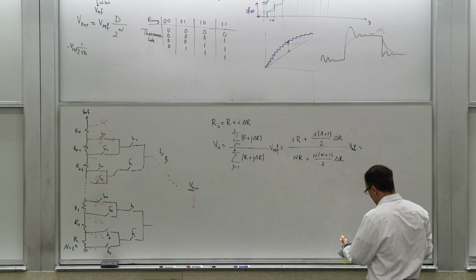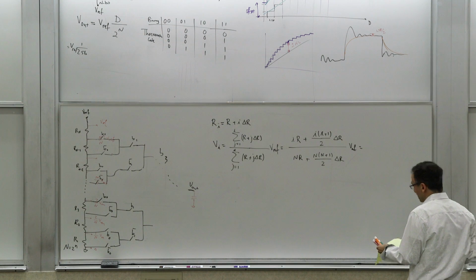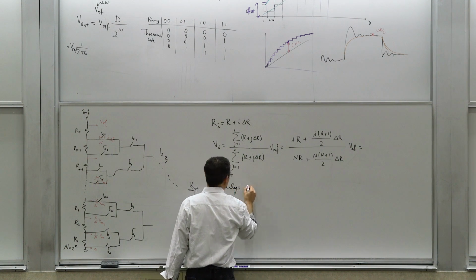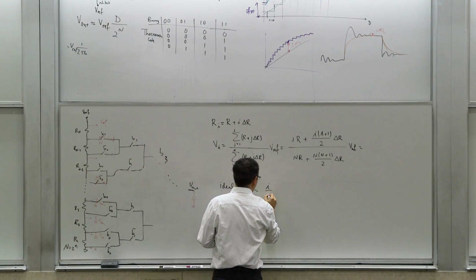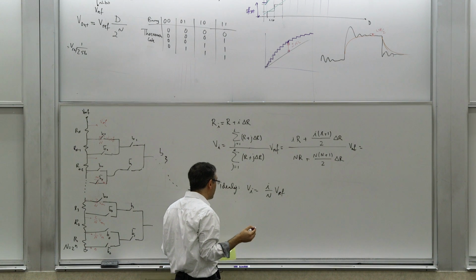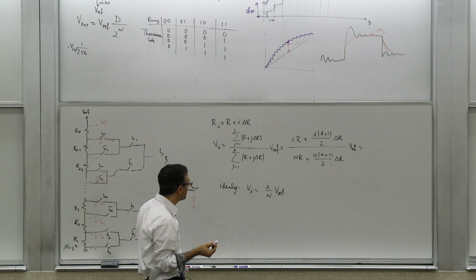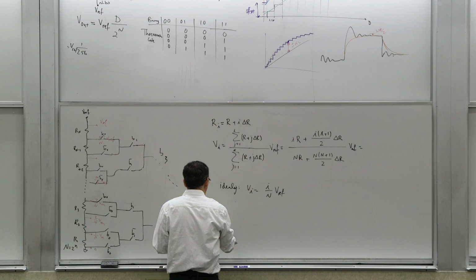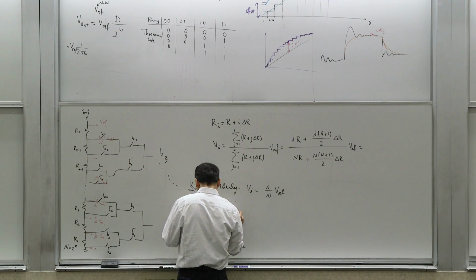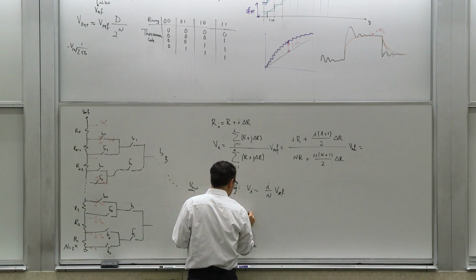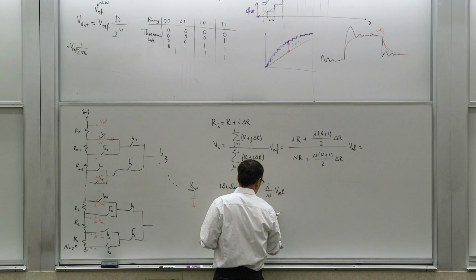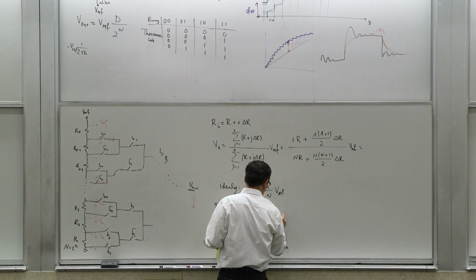Okay. Now, if you have this, then the ideal voltage at the tap I, so ideally, Vi should be I over N times Vref. Now, what we are trying to calculate is a deviation from that. So if you want to calculate the deviation from that, for example, you can think about the INL, right? The INL at tap I is going to be VI ideal minus VI actual, which is this.